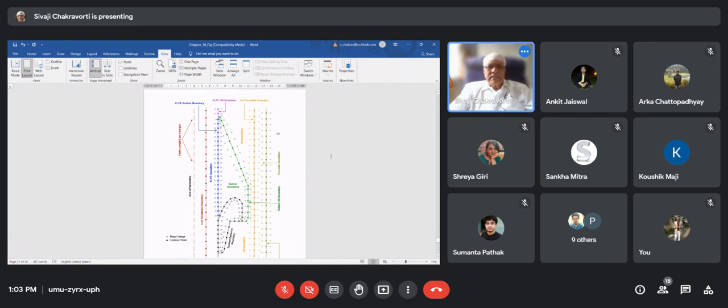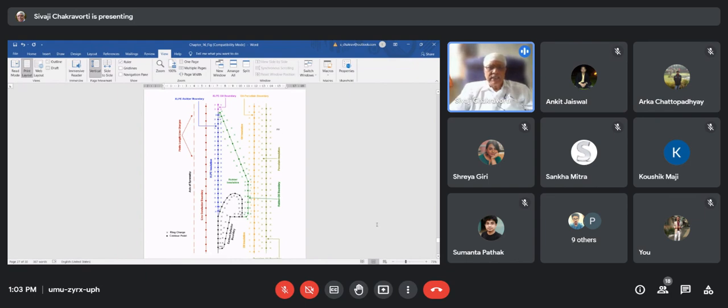What is it? This is actually a bushing. Now, this is a very actual bushing, so it's a complicated one. A bushing has a live conductor at the center, that's the red one. That is straight away a cylinder, the central red part. Now, that is not of infinite length, so it is a cylinder of finite length. So we will put some finite length line charges. As you can see my mouse moving, this is the red part, the finite length line charges.